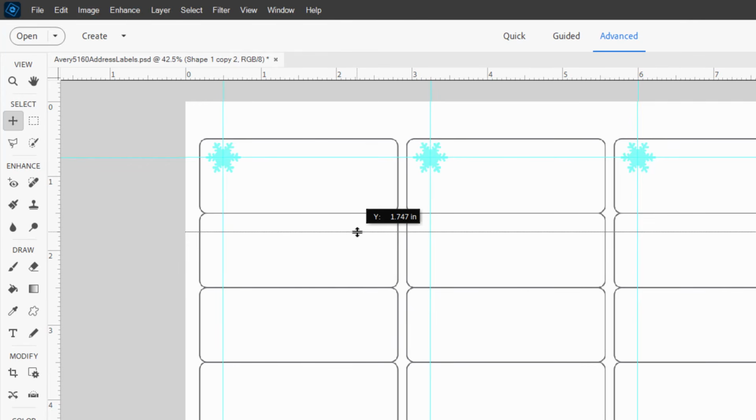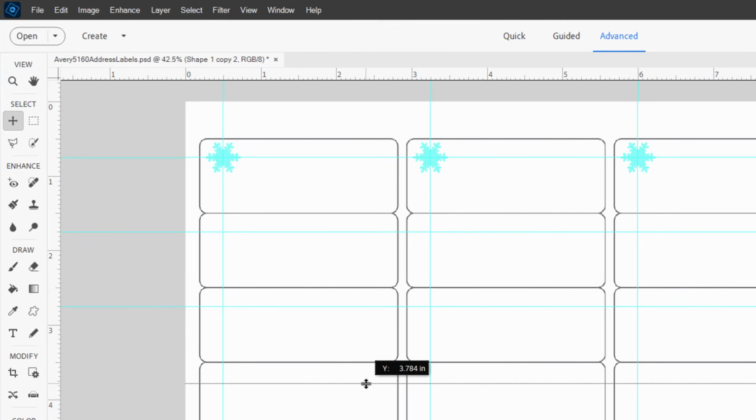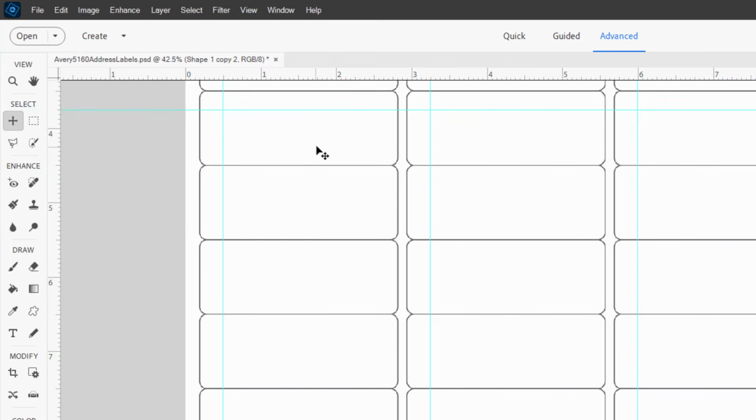Either use the view to put a new guide at that point, or just go ahead and put it in manually like this. This is oftentimes just as easy. So just look at the left side ruler. There we go. And just come in and bring these down. So I'm putting them all at about 3/4 of an inch. Like that, we'll just go down the whole page here.